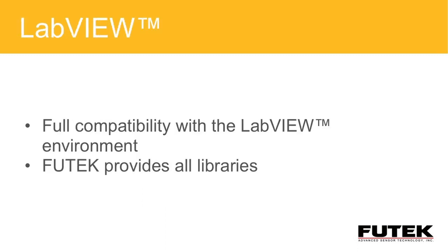The last option that we're going to cover today is LabVIEW. FUTech's USB DLL is compatible with LabVIEW. LabVIEW gives you the ability to use .NET assemblies through several .NET nodes. You can instantiate a .NET object, you can call a method on a .NET class or object, and you can access a property on a .NET class or object. LabVIEW provides all of these features through the functions palette using the connectivity and the .NET extensions.